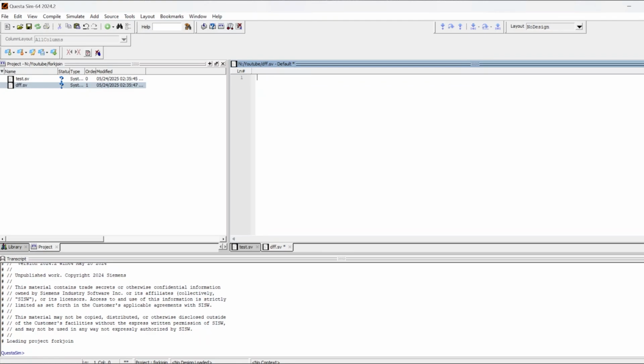So this makes it very easy, and also during the port declarations in the top level module, you just don't have to mention and declare those common signals again and again. So it reduces the redundancy and some possible errors.